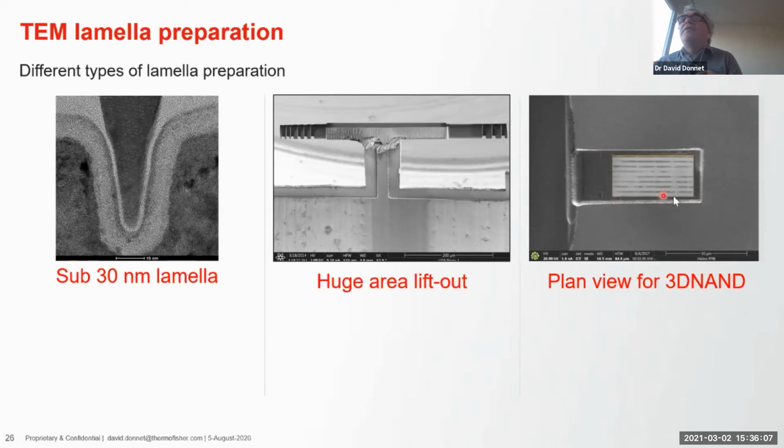This is about 30 by 15. That is very difficult to achieve by normal circumstances. So again, this is something where the plasma FIB really takes over. So that's just a short overview of what you can do for TEM prep. Really is possible, and there's a couple of nice examples that gallium cannot do. So that's the main applications for the semiconductor industry in plasma FIB.